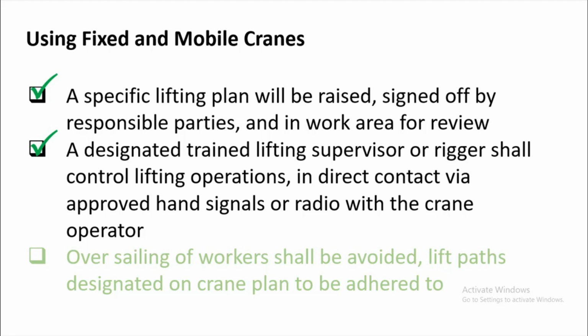You cannot assign riggers for only one day. You give them training now and then you assign them to rig the lifting operation. This is unacceptable. He cannot be competent unless he has experience and has training on lifting operations. And of course, he must pass the examinations for rigging work from a third party.